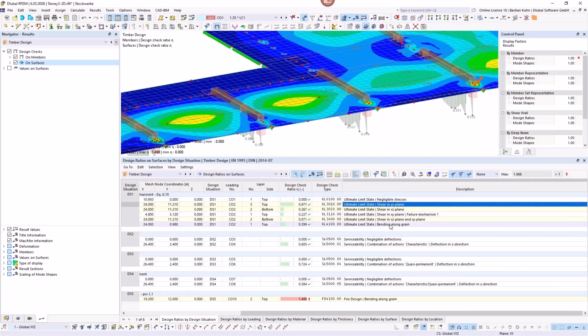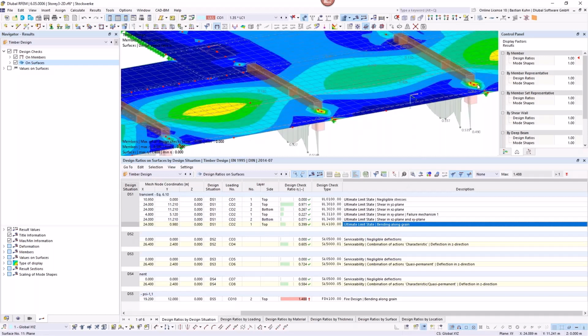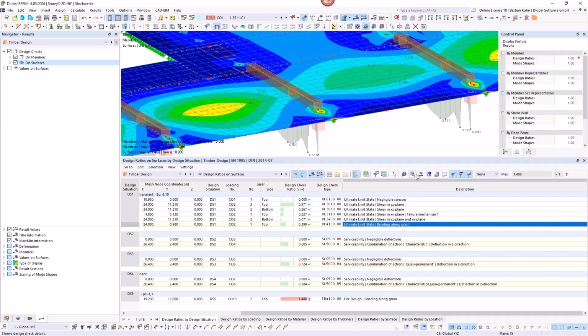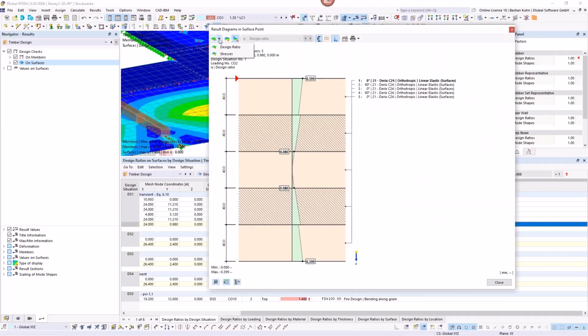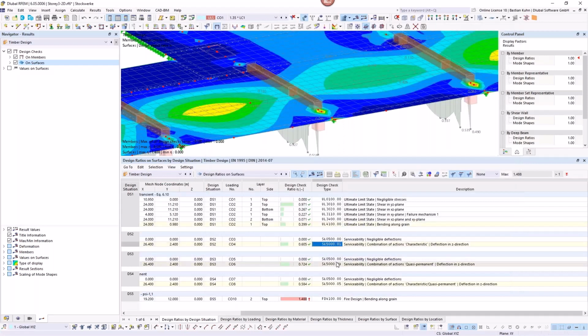Yeah, the shear for the punching-through area is given in here on this part. That's the usual punching-through area that you want to take a look at. And we can maybe also take a look at the stress over the whole section, because I think that's always nice to see. And you see for the bending how the stress is transferred into each layer of our section or our surface.